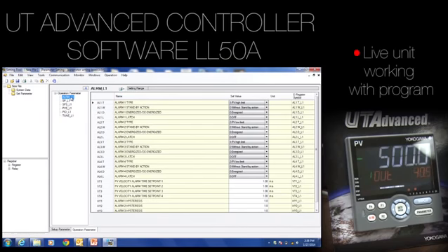The other thing about this controller that's really nice, that most people don't even think about, is this controller is also a small mini PLC. So that PLC capability is built into this. So this is full-fledged ladder logic, DIO, the whole nine yards. So with that, we can turn that capability on. So make sure you show this. If you don't do anything else, make sure you show the ladder capability.